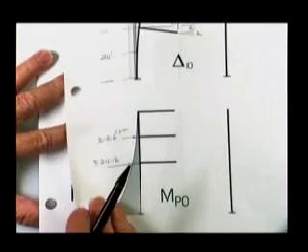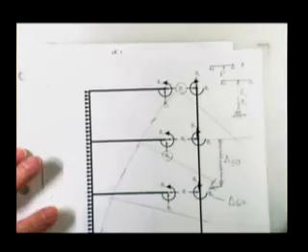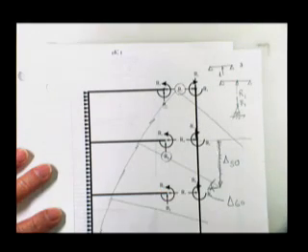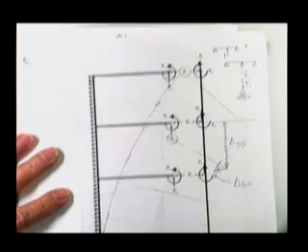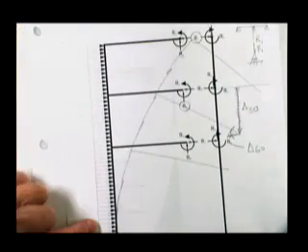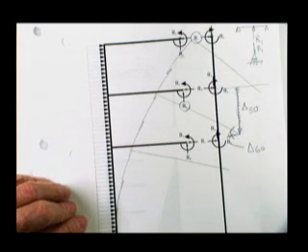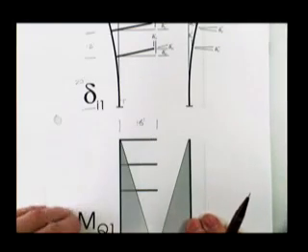Now, if instead you say, what I'd really like to differ from your analysis is I don't think R1 pushes on this member and pushes on this column. I think it really pulls. Then all of the tension sides due to the unit loads would change, but the tension side due to your real load would not change. You'll still get the same answer that I'll get. There won't be any difference in the answer. All right, here we go.